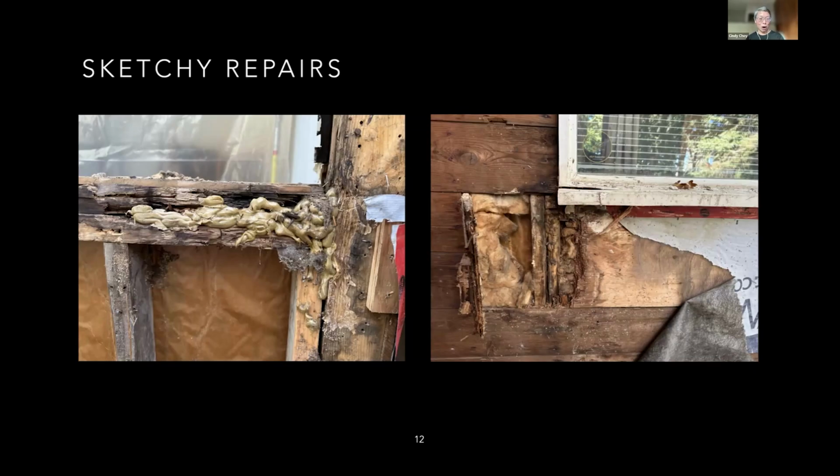They fixed rot by jamming it full of glue on the left. And on the right, you see an image as we're starting to do our exterior installation for our deep energy retrofit. They fixed the rot by replacing it with plywood, but didn't fix the original problem, which was the windows and the flow of moisture off that sill into the building wall.